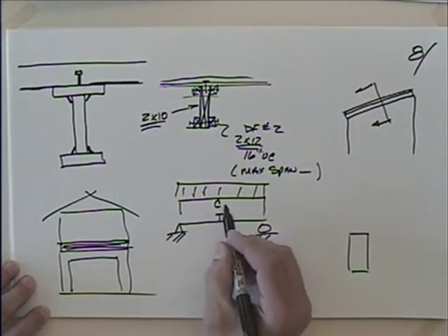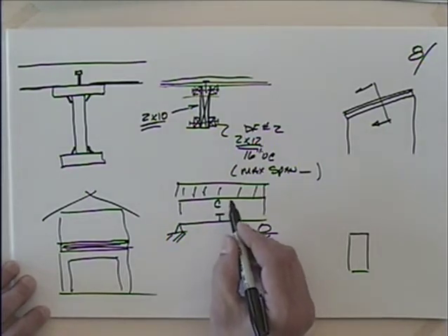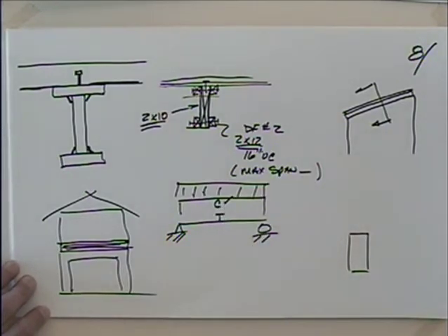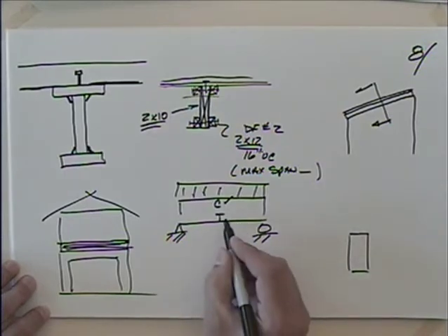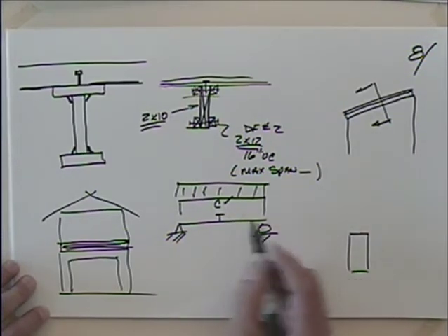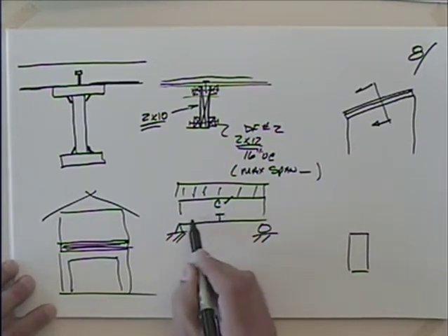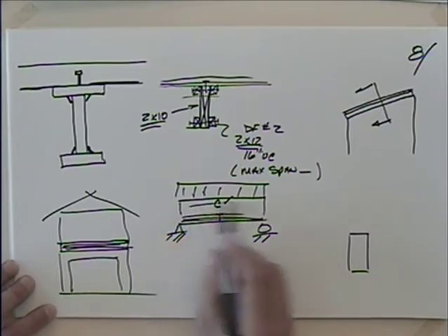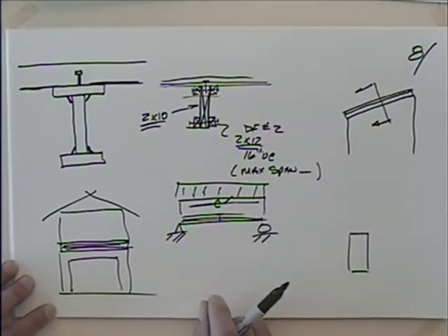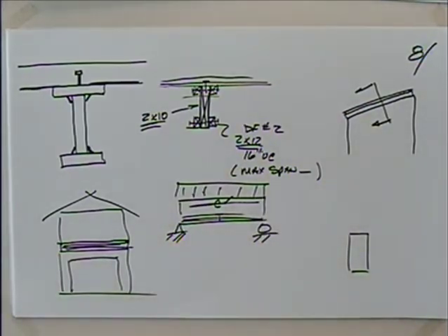And let's see, knots and kind of bad, almost rotten wood. Works pretty well for compression, right? But how about tension? You want good wood in tension. You don't want to have a bunch of big knots and whatnot. So what they do, if you have a, we call it an unbalanced beam, they put the really good wood in the bottom and they put kind of junk in the top. That actually works really well, okay? And you get the beam for less money.